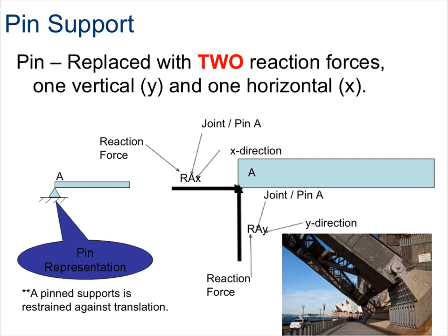Again, it's important to label these reactionary forces. So the pin support, we will call the reactionary force of pin A in the X direction, as well as the reactionary force of pin A in the Y direction. Lastly, make sure to note that the representation of a pin support is a triangle.